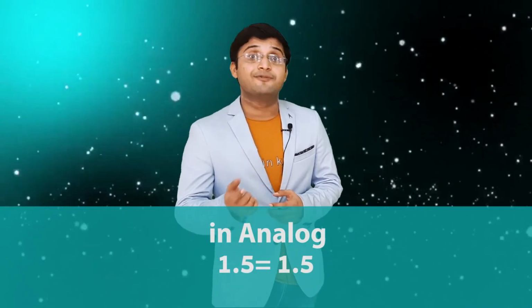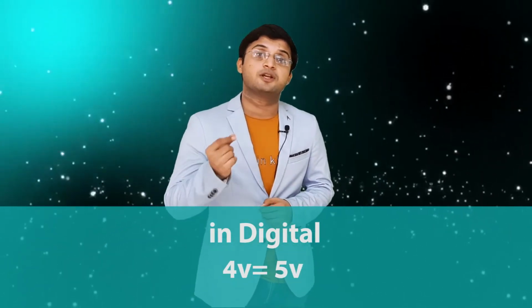So that is called analog signal. So if you have a sensor which gives a value like 1.1 or 1.035, so that value also you can read in analog. But in digital, if you give 1.035, it will read 0 only. If you give value 4 volt, it will read 5. So in digital pins it can read 0 and 5 only. In analog pin it can read 0, 1, 2, 3, 4, any value from 0 to 5 volt in the analog pins.